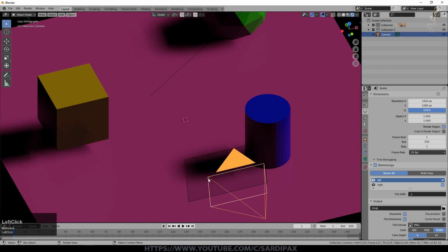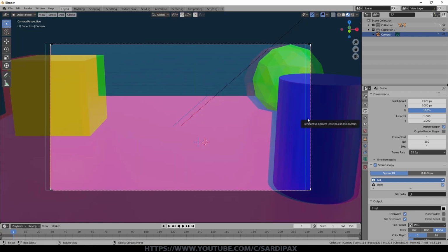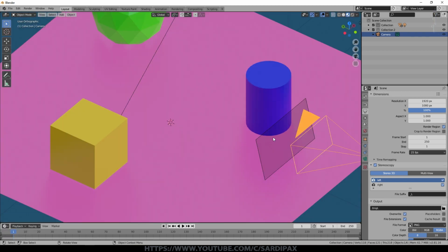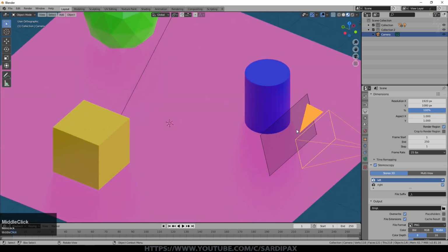Now you'll notice when it's in this 3D camera mode, there's actually a little plane appearing in front of it. That plane is the convergence plane. My rough understanding of that is that that's the point at which the two eyes are focused. So it's not actually to do with focus, but it's to do with where the eyes are pointing at. And essentially anything behind that plane, if you imagine the screen within here as a window through which you're looking, everything behind the convergence plane is outside, behind the window. If you bring anything closer than that convergence plane or push the convergence plane back, then they will appear in 3D terms to be in front of the window.